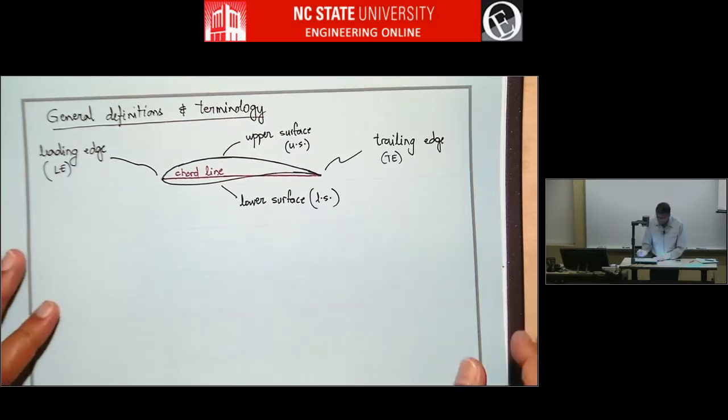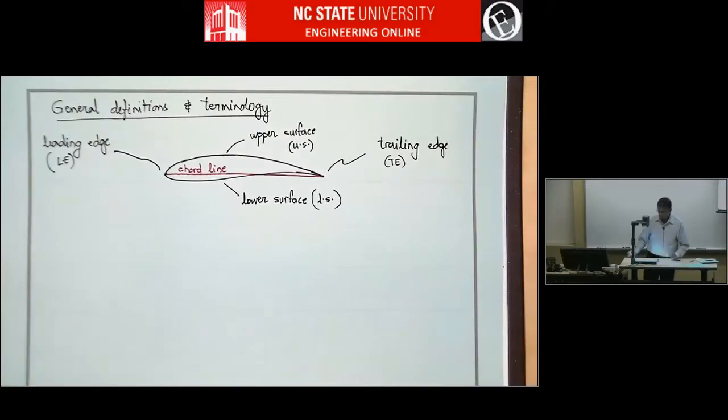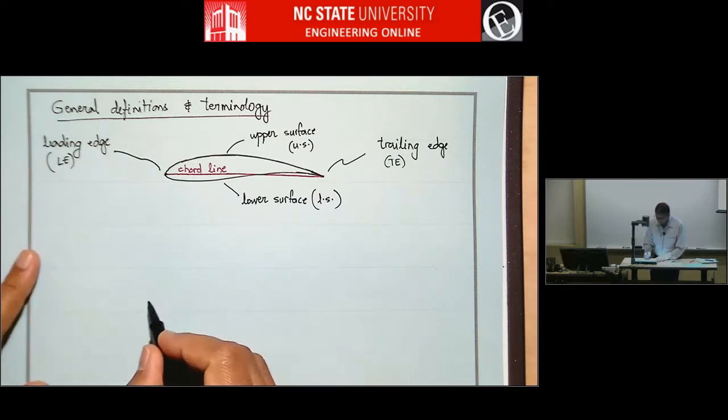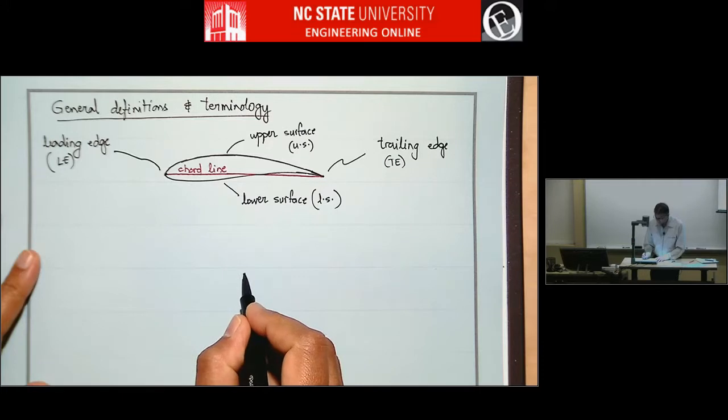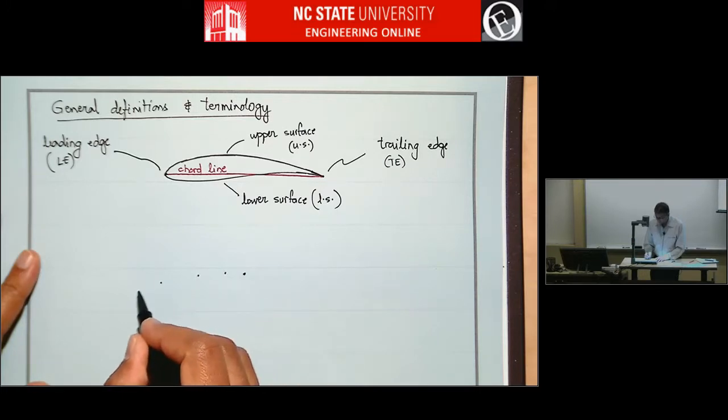What I mean by that is, let's say you have some airplane available to you that you're reverse engineering and you want to figure out what airfoil that airplane is using. You can take the wing and put it on some kind of coordinate measuring machine or geometry scanning machine and it gives you coordinates like this. It will give you the trailing edge and then all these points.